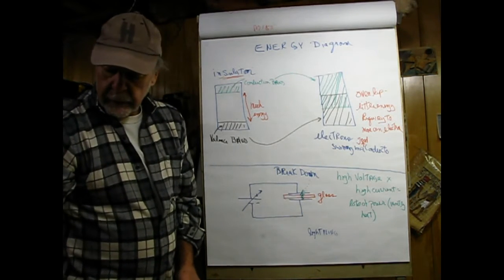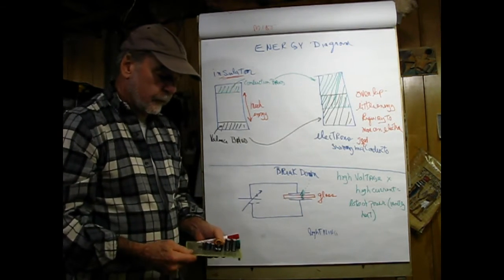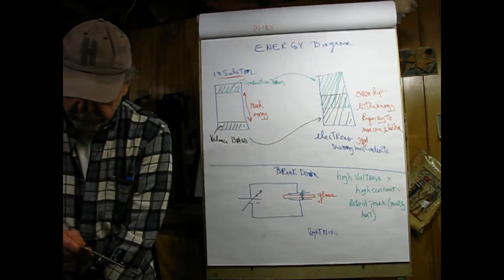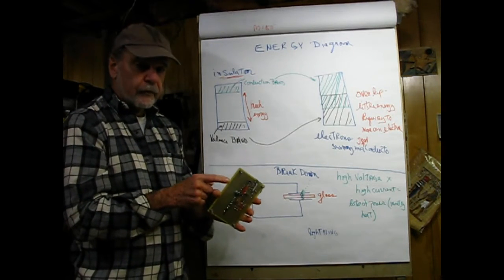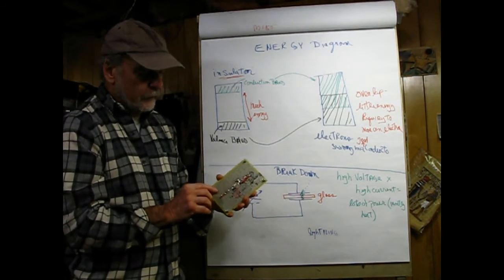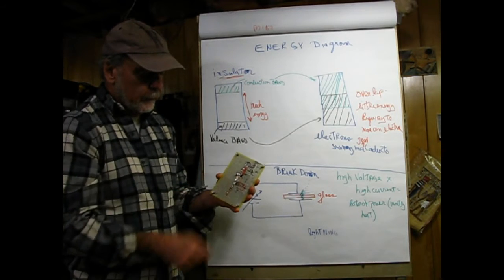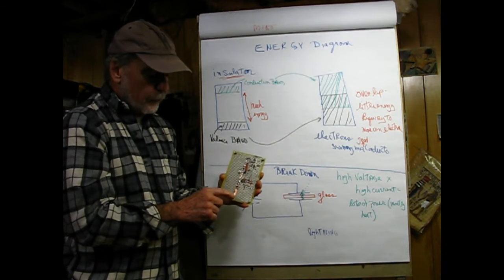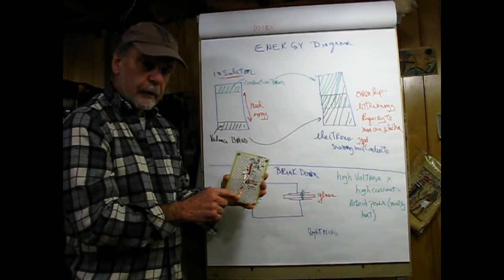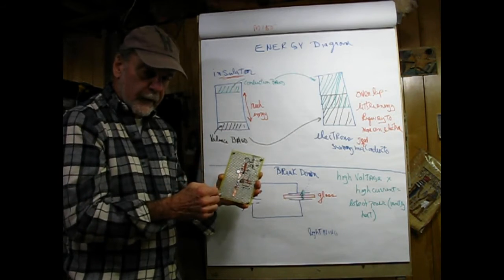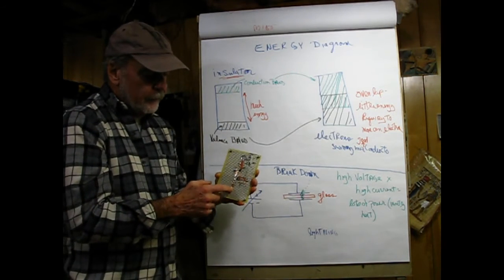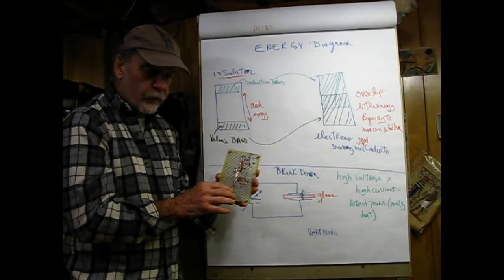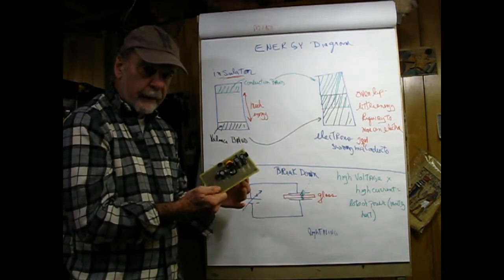And just to put this into perspective, this is a prototype I'm working on, and the green you see here is a circuit board. It's epoxy glass, and it's a really good insulator. And then the actual wiring, as you see over here, is made of conductors, of course. This here is a piece of copper stained glass tape. You put it around stained glass and then you solder them together. And it's the ground, and that has to be a really, really good ground, that is to say low resistance, in this particular circuit, or bad things happen.